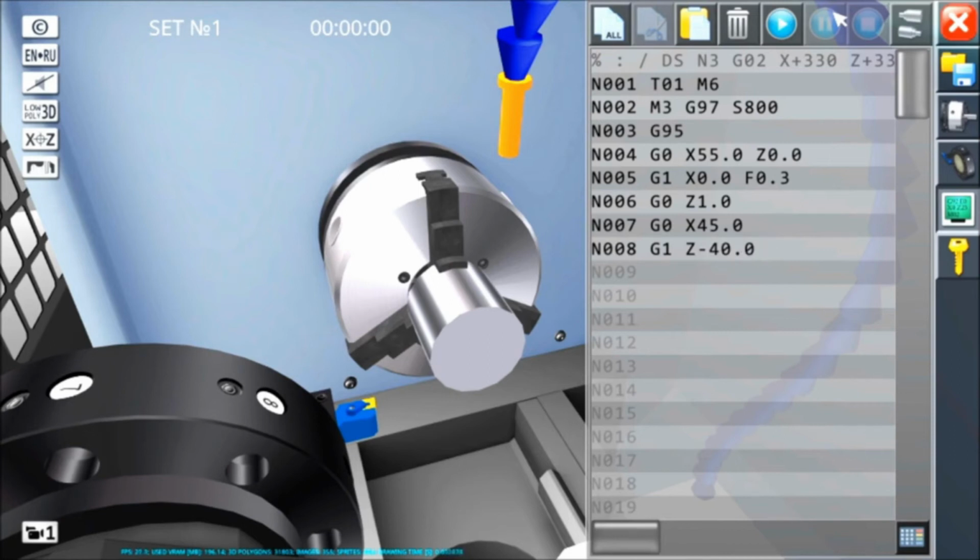Having finished my machining in rapid G0 X150.0 Z50.0, I detach myself from the workpiece and write M30, an M saying, well, you've finished, rewind, we'll start a new workpiece. I run it and see if it gives us any error.